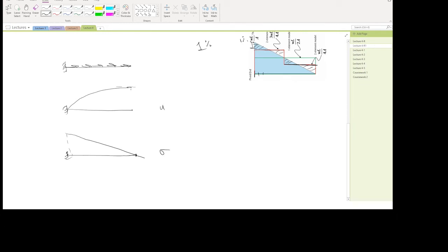All right, so we are trying to interpolate this with shape functions N1 and N2 that would use lines to interpolate the displacement. So trying to use lines to interpolate the parabola, and it is going to use constant to interpolate the stress. Now, how about instead of using lines to interpolate a parabola, how about using a parabola to interpolate a parabola as a second order interpolation for the parabola?